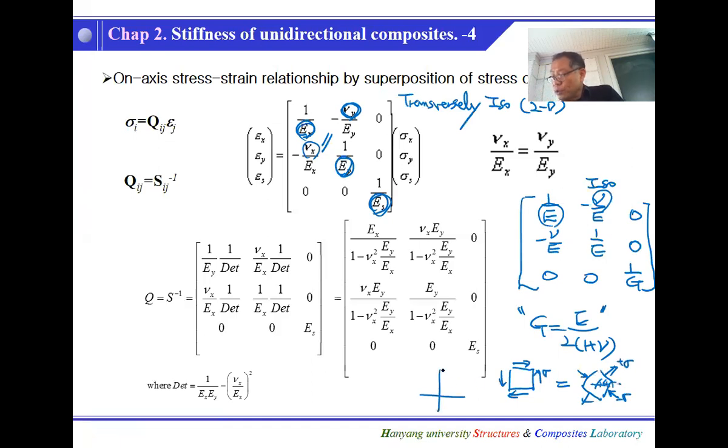If you look at the, I hope you remember, the Mohr circle. In the Mohr circle, this shear stress is here. And if you rotate 90 degrees, or 2 theta, which means 45 degrees, this is exactly tension and compression. So however much you apply shear stress at 45 degrees, one way will be compression, the other one will be tension. So this is the tension and compression, and this one is exactly the identical stress state.